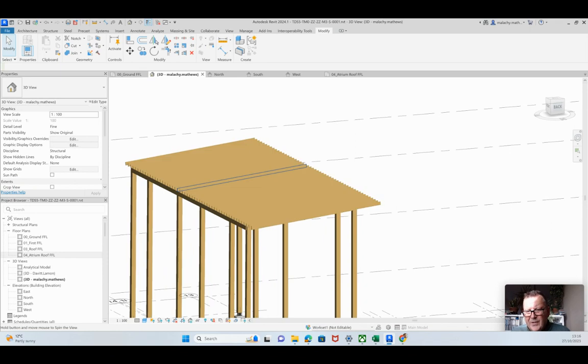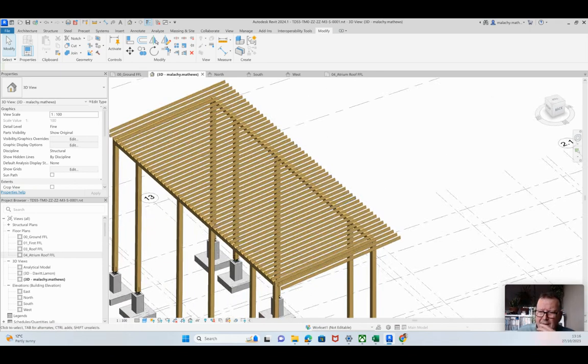Now, that is more or less the makeup of the structure of my roof here. What I'm going to do then is go into the roof tool and put a roof structure in on top of that. I'll probably have something like 175 insulation. I'll have some type of board and building paper or a membrane or something like that, something on which I can lay the zinc. Okay, and then I'll run the zinc all down this way.